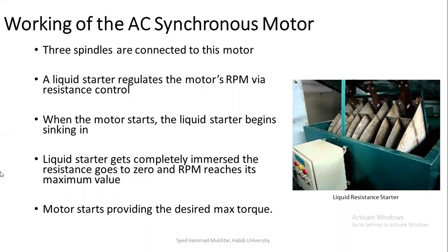When you talk about the 3 spindles, the top and bottom spindles spin clockwise in order to carry the red hot steel through the forward passes, the forward rollers, while the middle spindle spins anti-clockwise in order to carry it through the backward rollers in order to smoothen out the billet.